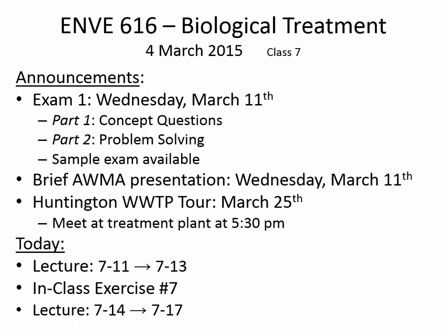Does anybody remember when we were talking about BOD bottle testing? So why would seeding be required? That wasn't the one that I had in mind. Now that would be dilution. Exactly. The classic example is if you put sugar in water and do a bottle test on just sugar water, there isn't going to be any decrease in the oxygen content because there's maybe no bacteria to use the substrate. So seeding is when you artificially add bacteria to the testing. So that's why sometimes you require seeding.